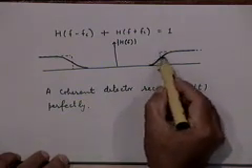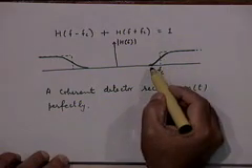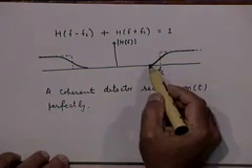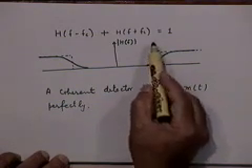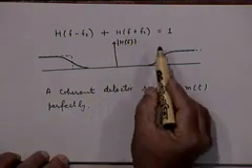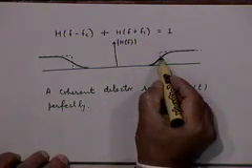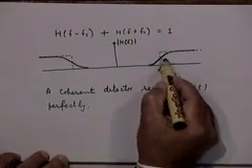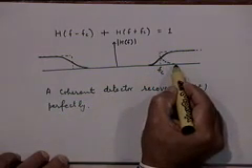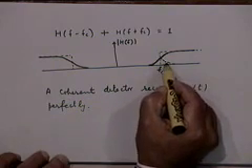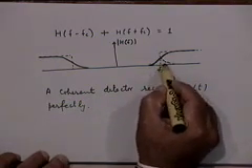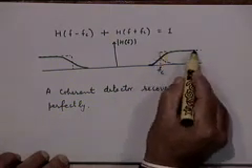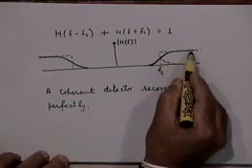Let's see what this constraint means on the filter transfer function. Can you guess what it would mean? It is a kind of symmetry that is implied here, right? If you, for example, look at this condition carefully, this is basically saying that if I fold this portion of the roll off back into this region, right, if I take a mirror image of this around this point, then if I add up these two curves, they should turn out to be a flat curve, a constant curve, right?